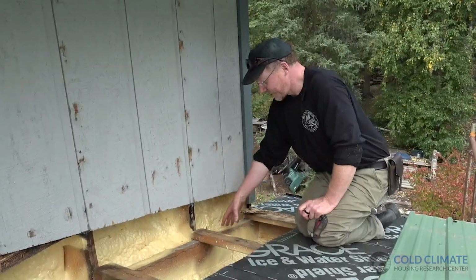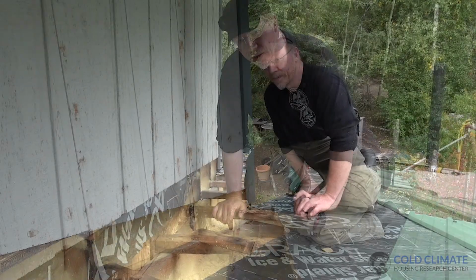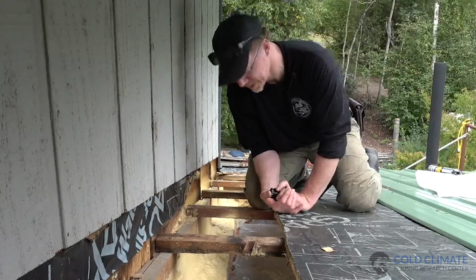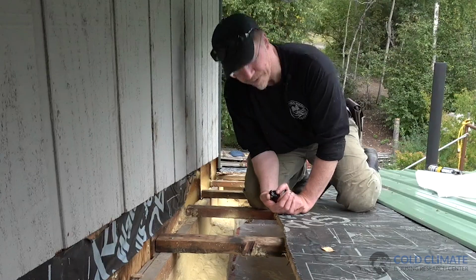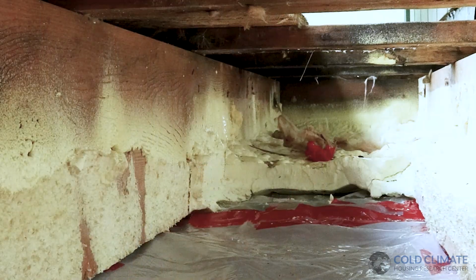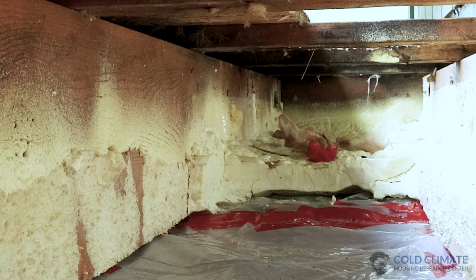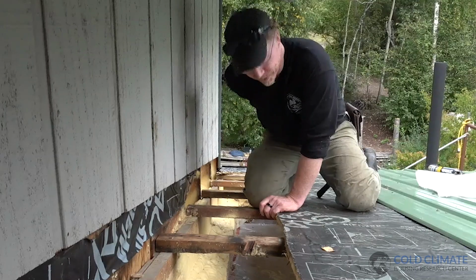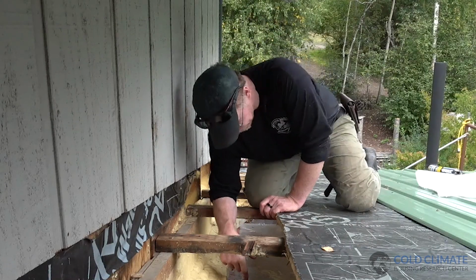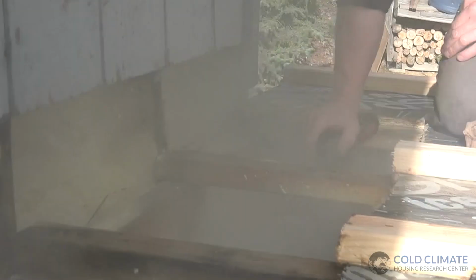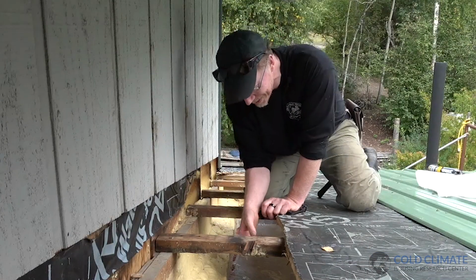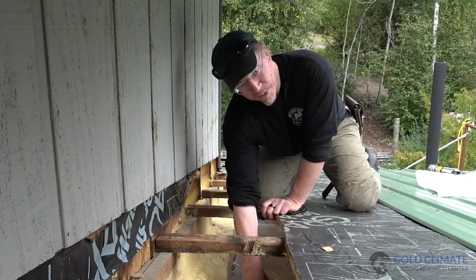So these have to be sealed and addressed as well. Our third problem is more complex. And the issue we found is the area above the closet ceiling that we had to cut away to inspect the roof and to let the moisture out. We saw massive amounts of smoke coming out of this area during the smoke test. In fact, it was so much smoke, we had to stop the test, clear the smoke out, and then we could see what the problem was.